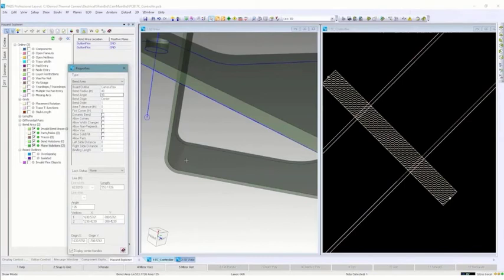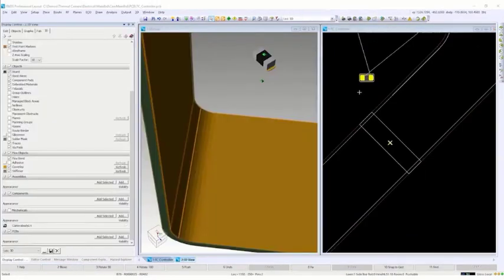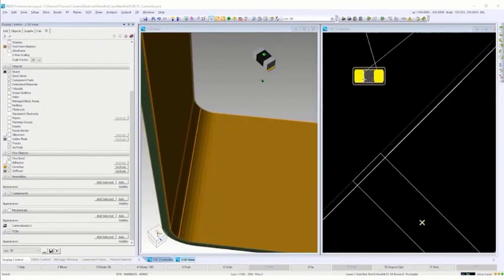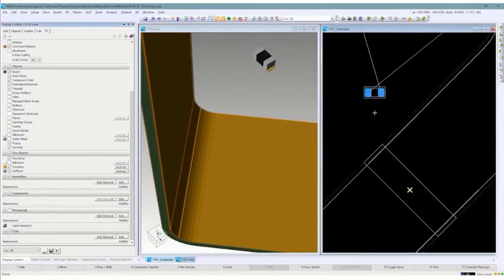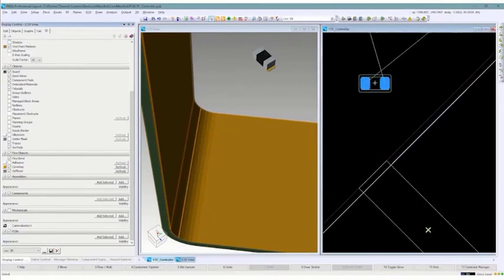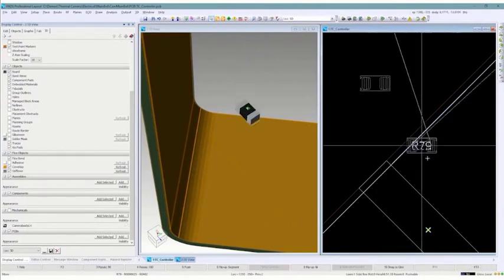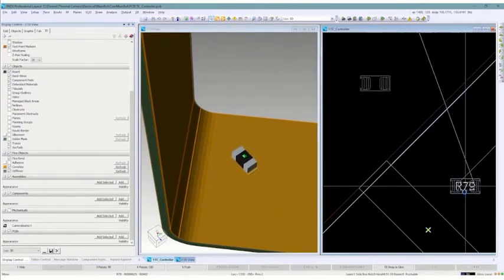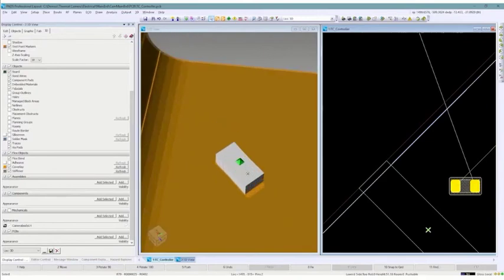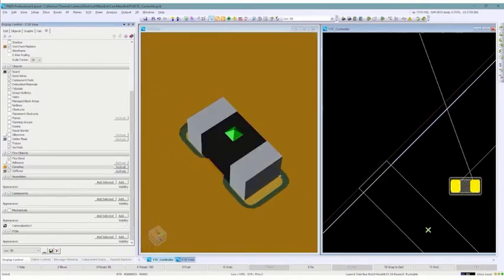Okay, so another example here is, let's say I take a component and place it on the flex relative to the bend area. The same thing would be if I'm routing and putting a via in. When we place our part on the board, this is another very important characteristic to pay attention to: when I add the part to the flex region, it's automatically going to switch the pad stacks over to rounded corners from square.